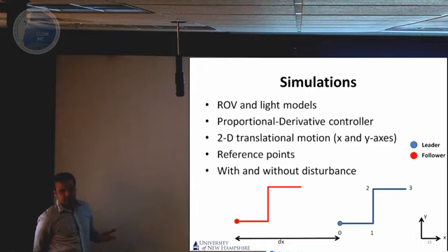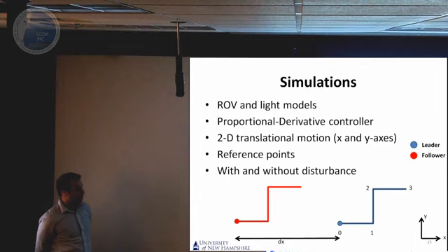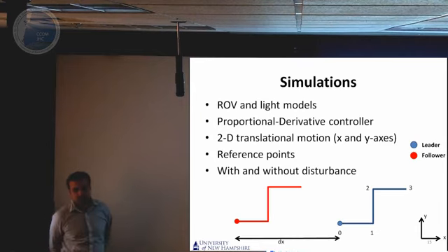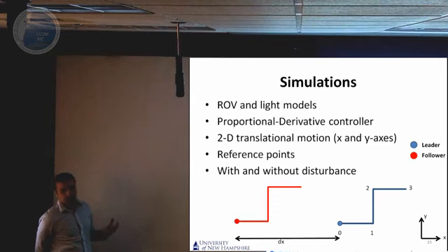One question here may be, why are you using a linear PD controller on a nonlinear system such as an ROV? If you go back and do the math, incorporating the controller dynamics into the equations of motion and doing the Lyapunov function analysis, it turns out to be stable in the sense of Lyapunov in the nonlinear system analysis. Also, it's used extensively in industry to control the heading of UUVs and ROVs, and also depth control for ROVs. The PD controller is widely used.